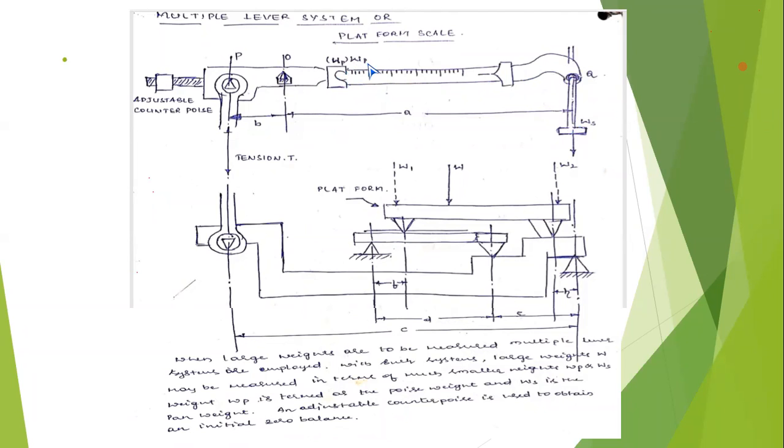Movable poise weight. So for example, if you want to measure 43 kgs, then what you have to do? You have poise weights in the denomination of 20 kgs, 10 kgs, like that. You place 20 kgs into 2 poise weights here, then it becomes 40 kgs, and move this movable poise weight on the graduation near to the 3 or after the 3.